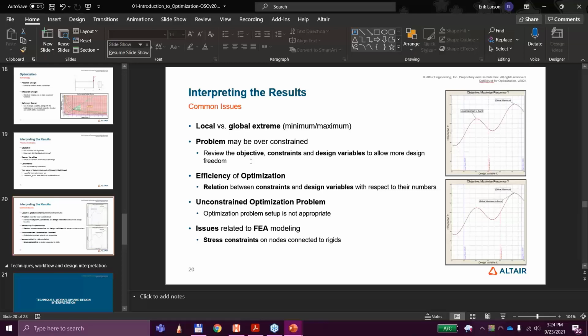And he is running the optimization, and when he takes a look at the result, the entire part of his design space has just been completely eliminated. It's all gone. He doesn't know what's going on. So we take a quick look at his thing, and it turns out he under-constrained the model. He needed to set a limit as to how much could be removed. It optimized it. It got rid of everything. It made it as light as possible. So mistakes like that can come up, and we need to take a look at those.